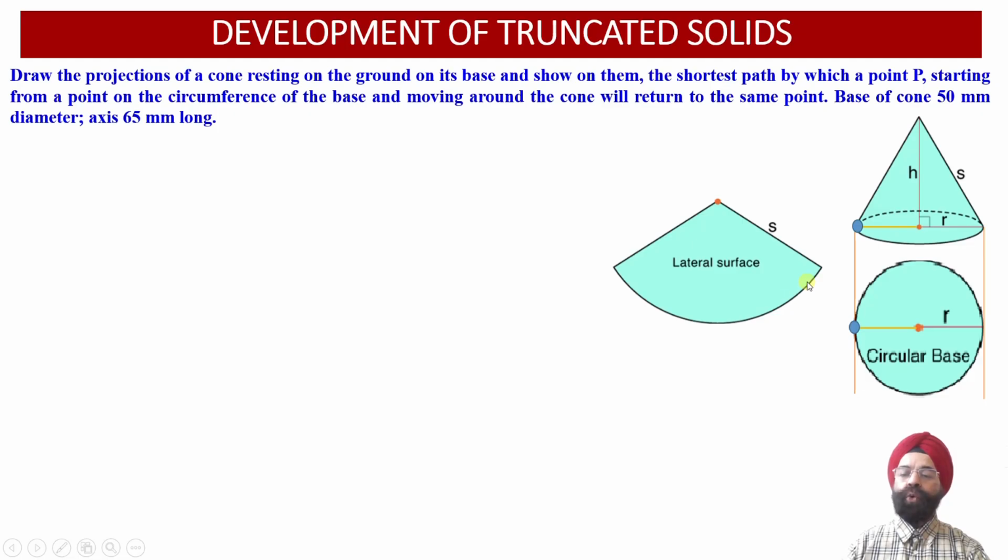So with respect to 8 or 12 generators, whatever points of intersections we will be able to obtain, those points of intersection we are going to bring back to the elevation view and the plan view, and then we will be able to evaluate the distance traversed by this point P or the B in the front view projections and the distance covered by this point P in the top view projections over here.